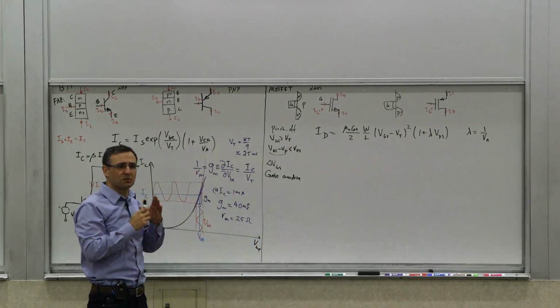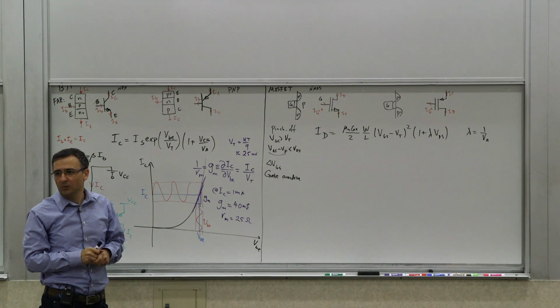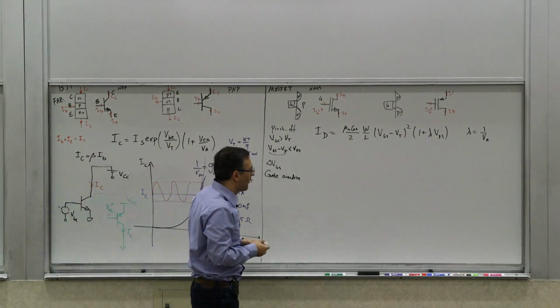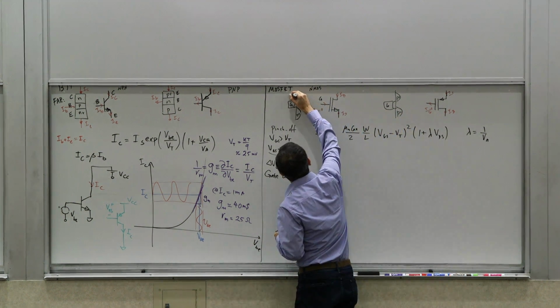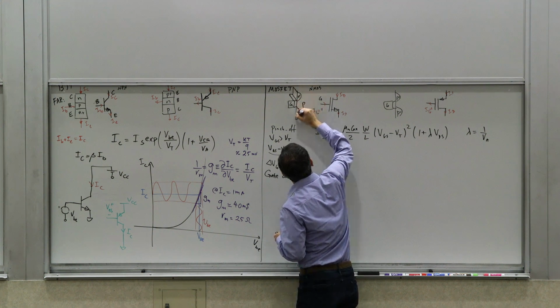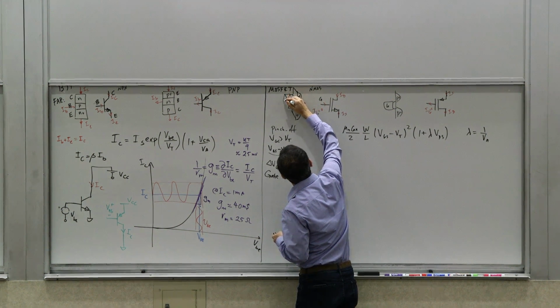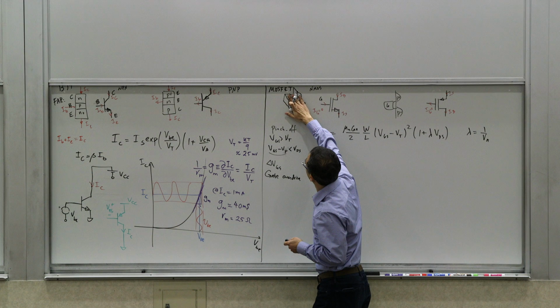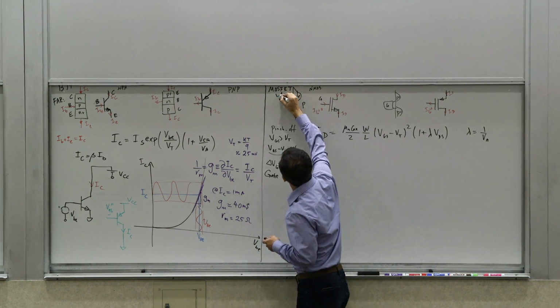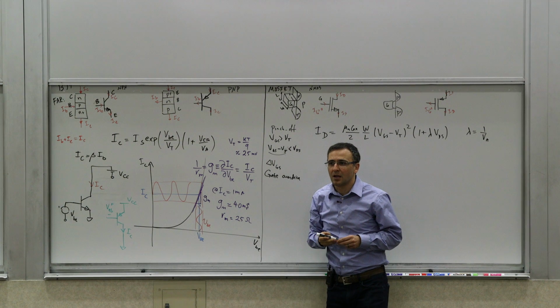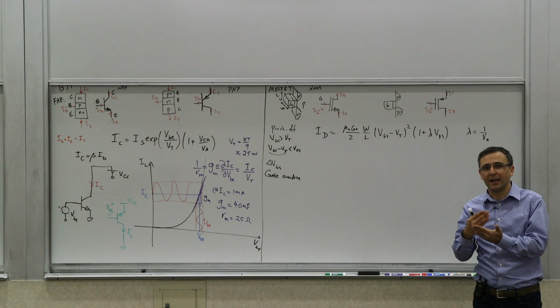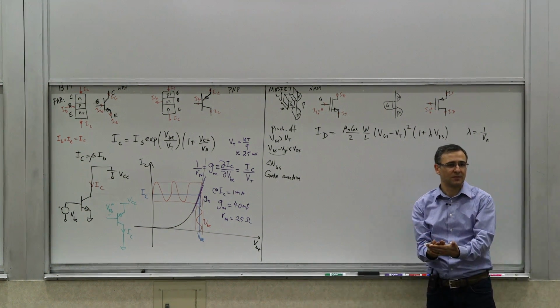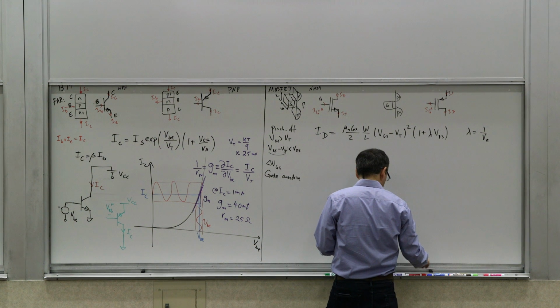And now, what do we mean by W over L? We've talked about this again, but this is an important parameter in the design as we go forward. If you remember the three-dimensional picture of this transistor, if you look at this three-dimensionally, this is the gate, something like that. This is the L, the channel length, and this is the W. Now, when you are making a transistor in a layout, you're looking at a top-down view. So the transistor will look like this.